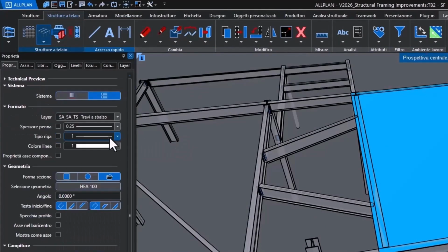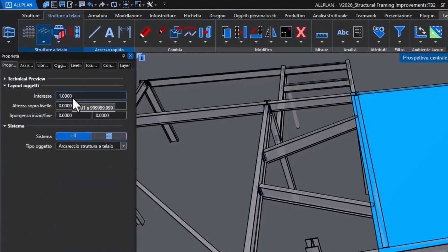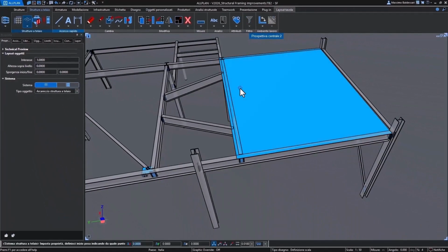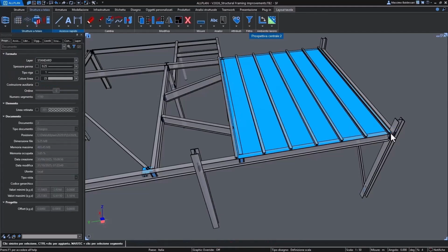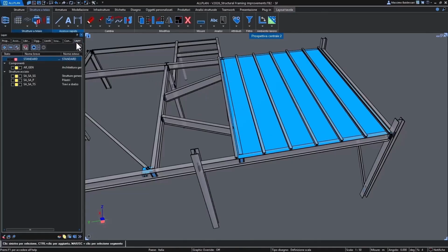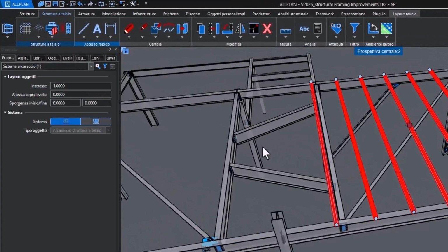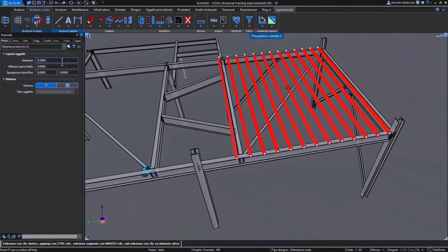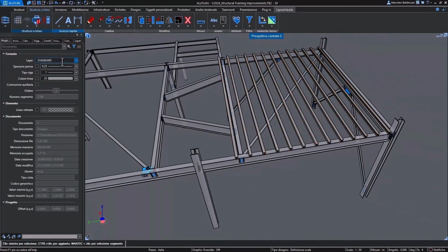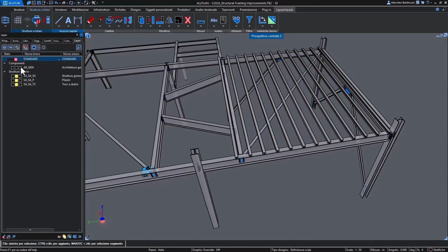The frame structure system feature simply allows you to easily place multiple different elements. So, for example, more beams, additional purlins, and so on, by just selecting the reference surface and then defining both a first and a second placement point within that particular type of surface. At this point, I could choose to hide the layer where I have directly placed my purlins. In this case, I would select them, and then I can more effectively manage their spacing or adjust other types of parameters or settings. The surface can be inclined in space according to your needs.